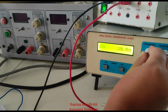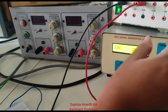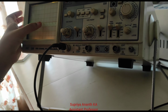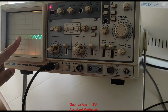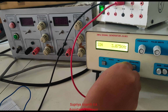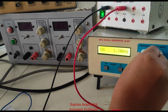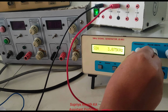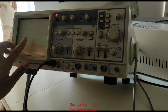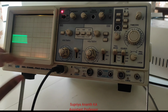Next, similarly vary the frequency to 200 Hz. Now you can observe this is 1 volt, that is 1 unit. So 1 unit into the time division 1, take down and calculate the frequency. Similarly go on varying the frequencies up to 3 MHz and take the maximum readings. At a certain point the frequency response will become constant, and by taking the readings, plot the graph and take down the calculation for the BJT amplifier without feedback.